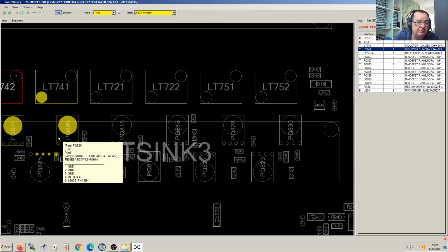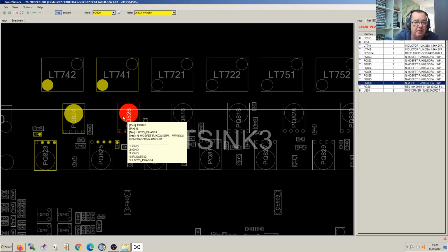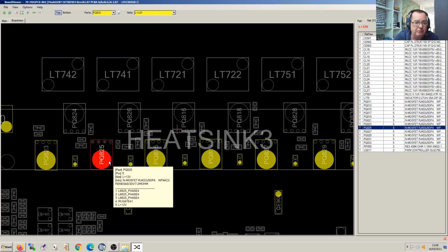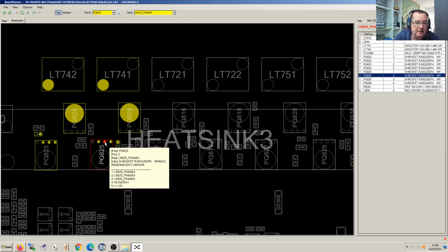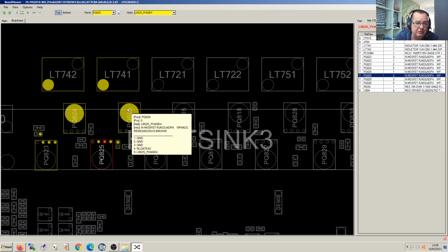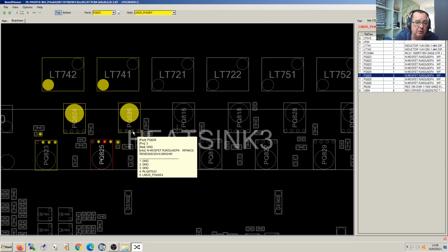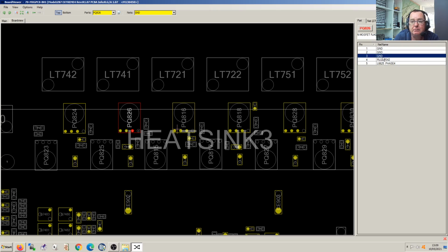But anyway, let's go back to one of our FETs. We've talked about buck regulators before, so we know that one of these is connecting to 12 volts. There, look, it says on the floating little box, 12 volts. This end here is connecting to the other one there and connecting to the coil. That's the junction between the two, and then the other end of this one will be going to ground, and it's showing us that. It's telling us on the floating box it's ground.